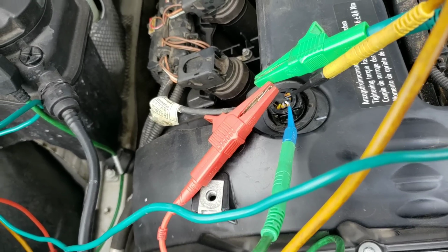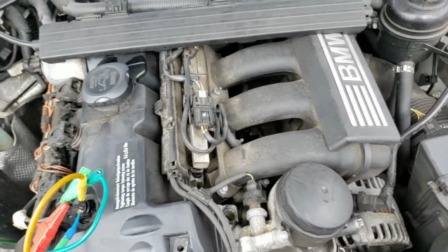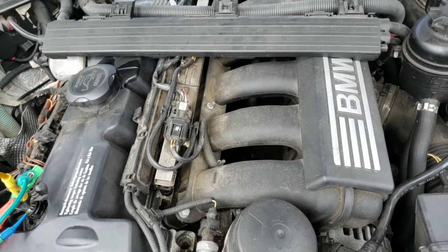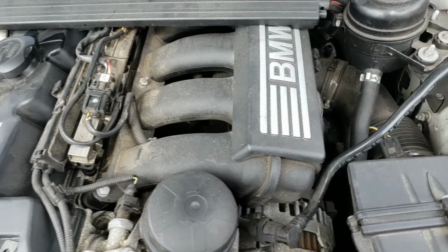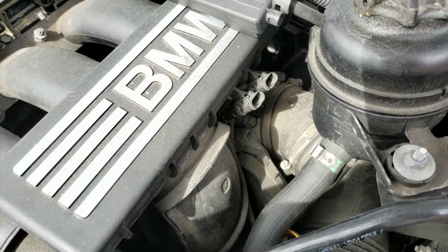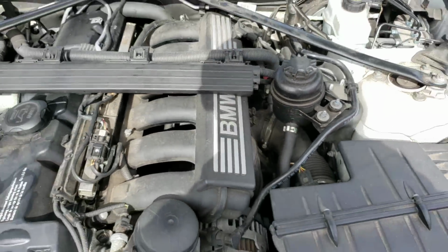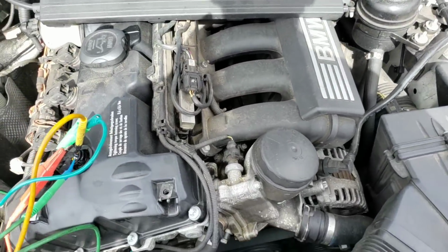But in a car like this, remember something. We have no intake manifold vacuum. Unlike other cars, they don't use intake manifold vacuum. If you were to go down there to that throttle body and pop it open and take a look inside there, that thing is open at all times.